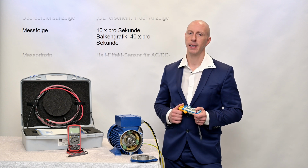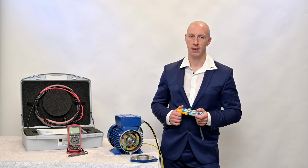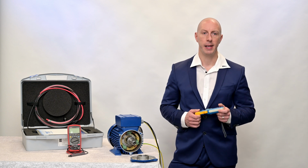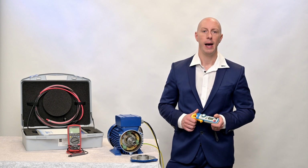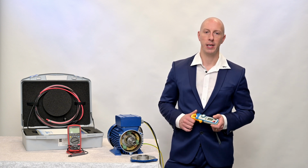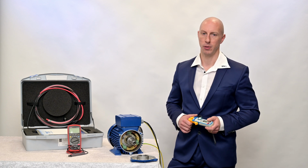In view of the fact that the bearing currents are rather high frequency, short, possibly very high current pulses cannot be recorded at all. Furthermore, it is more than difficult to evaluate the displayed value, as it does not provide any information about how high the dangerous current pulses are. Only an average value can be read. However, this information is indispensable for an analysis and subsequent selection of countermeasures. High pulses in particular are very important.